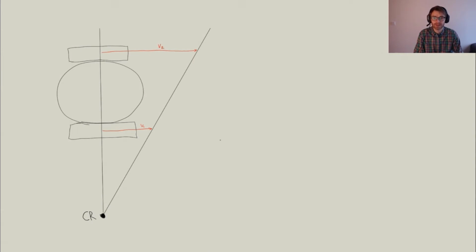What we have established so far is that we can calculate the velocity of the Turtlebot at wheel 1 and at wheel 2. Now in this situation, these two speeds are different, causing the Turtlebot to turn. So it's in a trajectory that looks roughly like this. It is turning around the center of rotation, which is defined by the difference between these two speeds, as you can see based on this line.